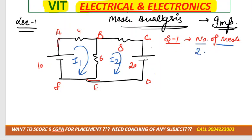Only 2 rooms means 2 meshes. One of the meshes is A, B, E and F, correct? And another mesh is B, C, D and E, correct? Okay. Now step number 2 is mark current direction. That we have done.